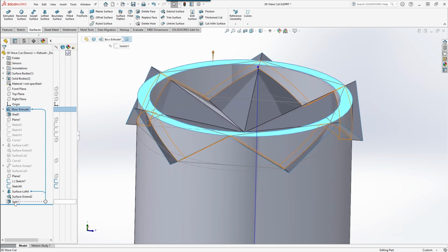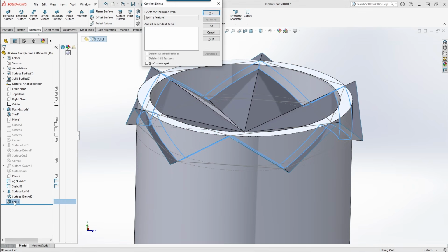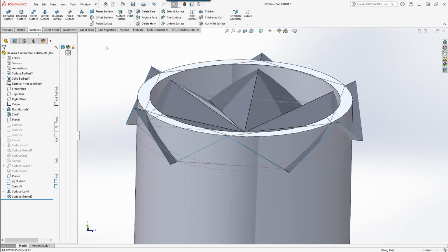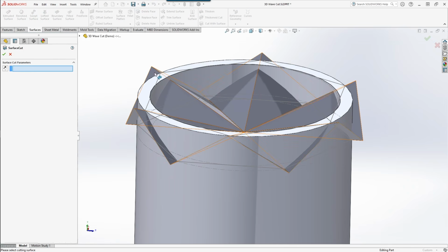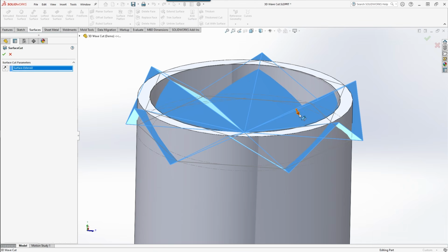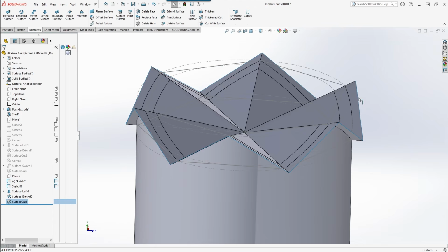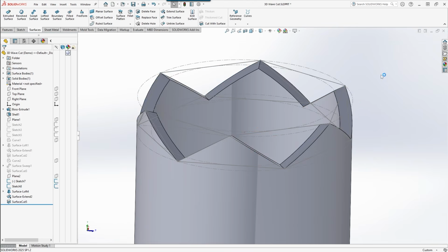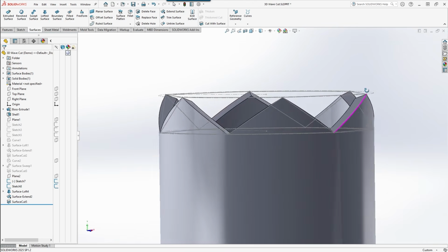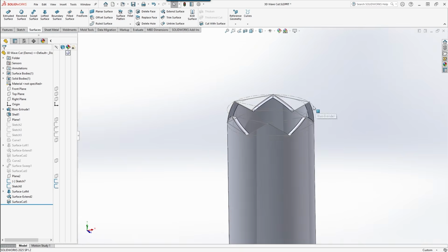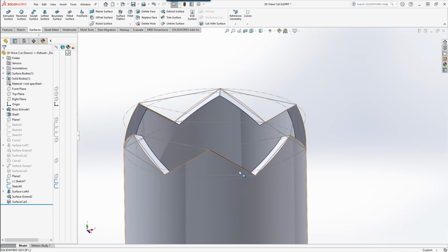Now, I'm going to go ahead and delete that split and show you the other way of doing it, which is cut with surface. So if you cut with surface, same concept, hit that surface, reverse the direction to make sure that it's going upward, and then you lose the second part, but you have a clean cut, and now you can see that you have that surface done. So you have the clicker pen cut out done that way.